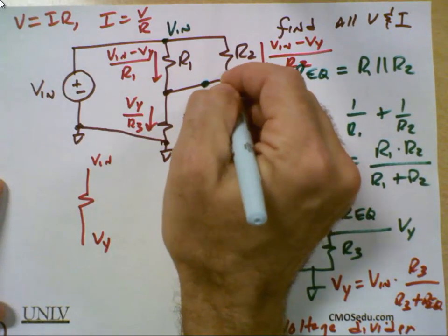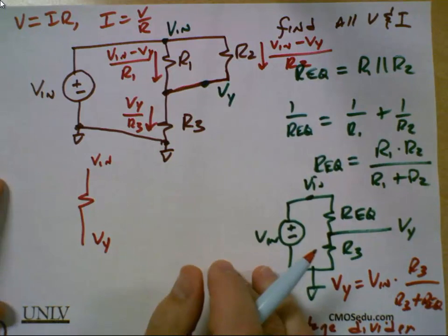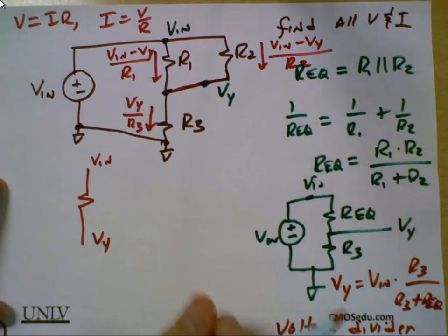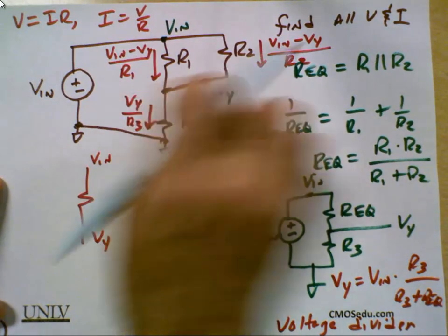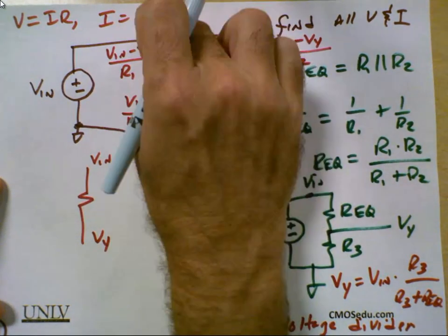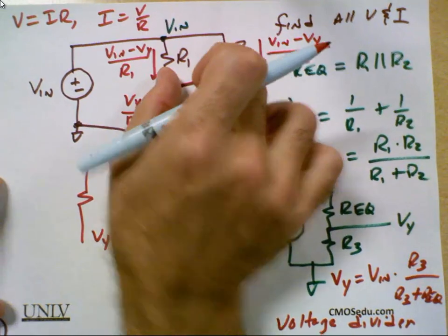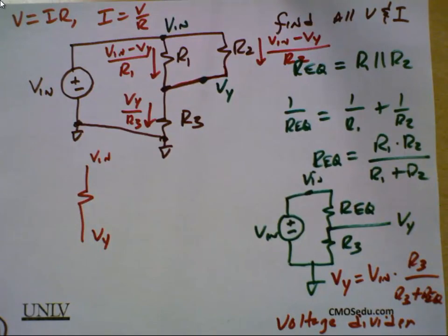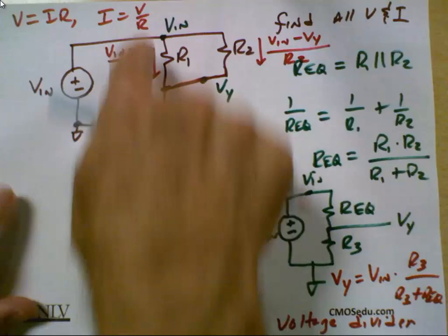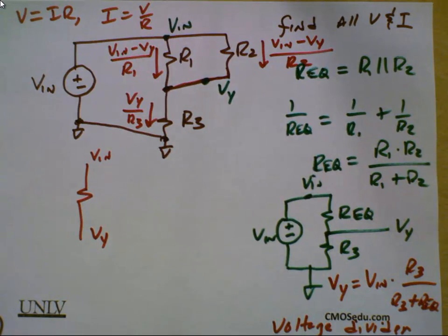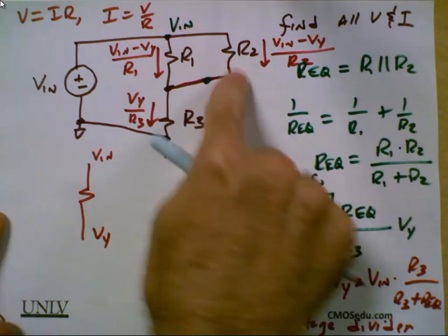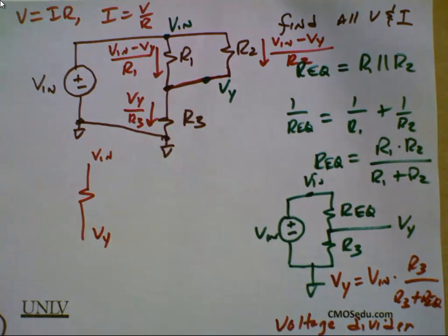Yeah, this wire, you assume everything's the same pressure. Same voltage. These drop some pressure before it gets to this node. So there's a higher pressure here, then it drops as it goes down. Like you could say, oh, well, you screwed up. You didn't put wide enough diameter pipes to supply your tools. Well, you could run another pipe in parallel, and it would reduce the pressure drop because now you'd have two paths for the air to go through. So this is just representing an equal potential, or a point where the pressure is all constant.